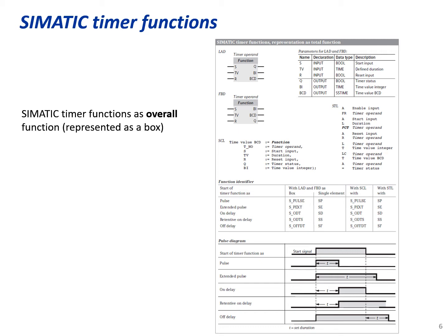So when it goes from off to on here, then after a delay of T seconds, the output of the timer becomes true, but the output will go off again when the start signal goes off. We have a retentive on delay timer, and retentive on delay timers basically keep the time, and you see that they don't go off after the start signal goes off, so it will stay on until we reset it.